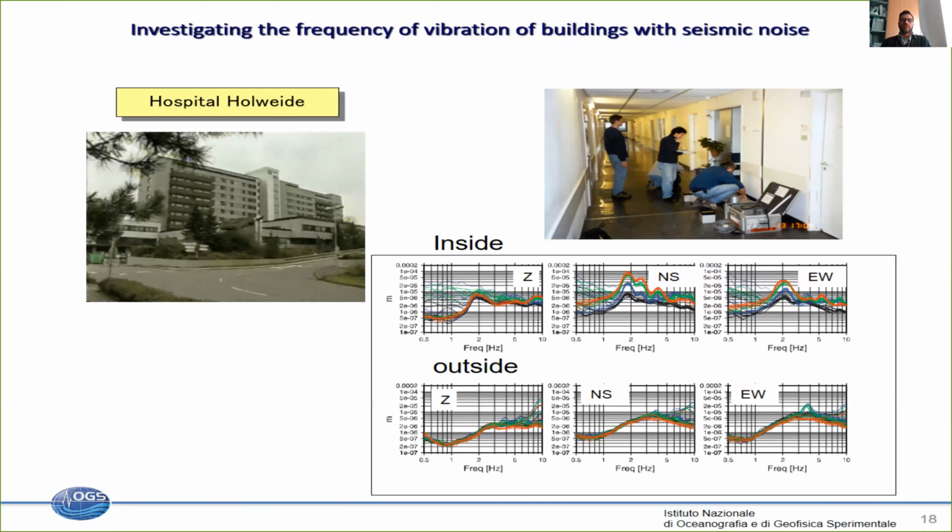Another important point for the noise measurement is certainly the analysis of also the structure. So as I mentioned, we are very much interested in understanding the frequency of shaking on the ground, because if this is similar to the frequency of shaking of the buildings, we can have a resonance and therefore damage can increase. So very often we use noise measurements also inside the structures to estimate, let's say, some parameters related to their dynamic behavior. So for example, the frequency of oscillations of this structure.